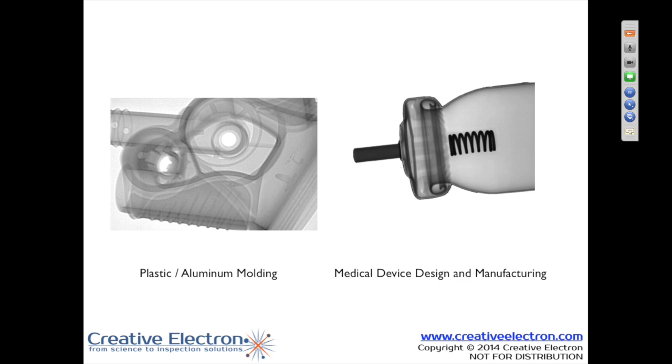If you look at all of the different aluminum components, even to the point of heat sinks, a lot of times when you buy your heat sinks, they've got some issues. So you may have some heat issues on your components, and it's because you've got a poorly molded heat sink.